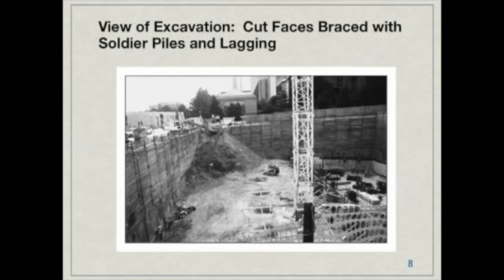Here we get a shot of a deep excavation. On the left-hand side is the support system, and this is the soldier piles and the lagging. In this case, the lagging is wood, but it can be other materials. The soldier piles are the steel beams that are driven right into the ground, and again, the lagging is the planks, the wood planks, that are bolted to the soldier piles as the excavation proceeds.